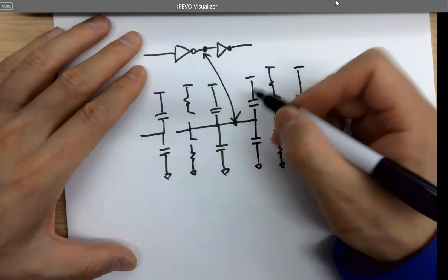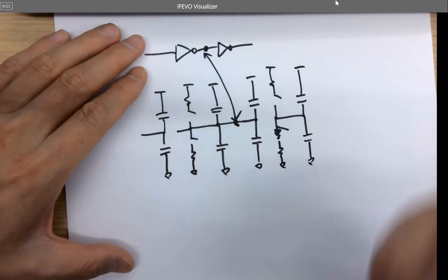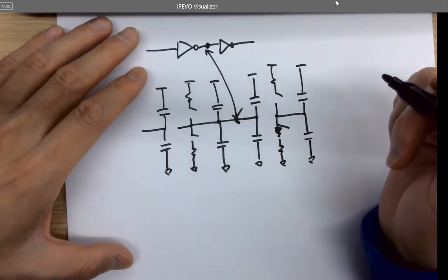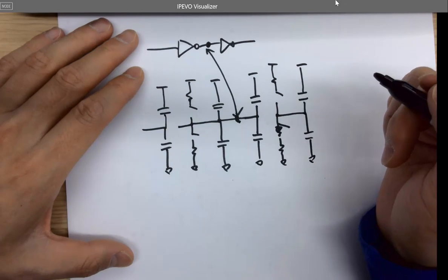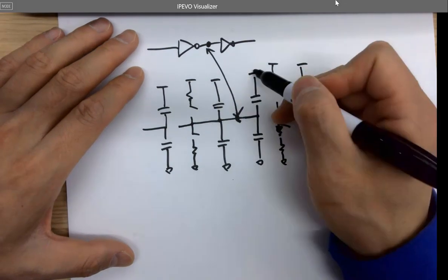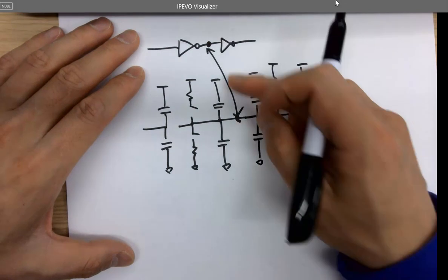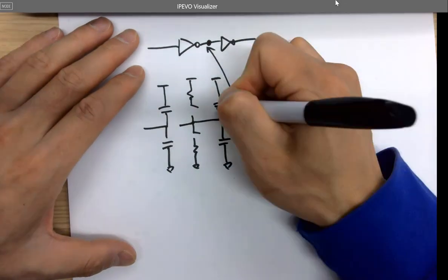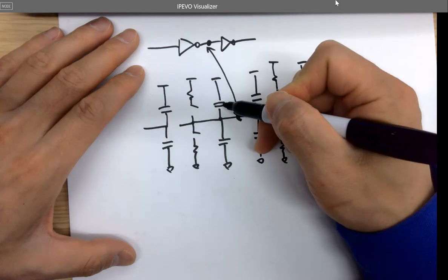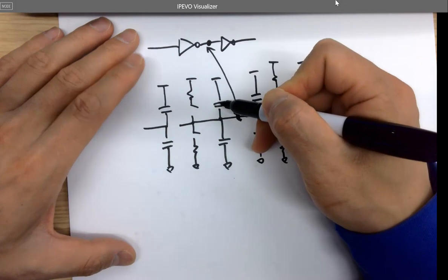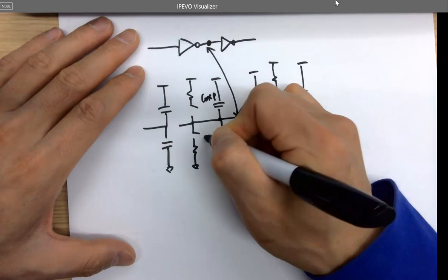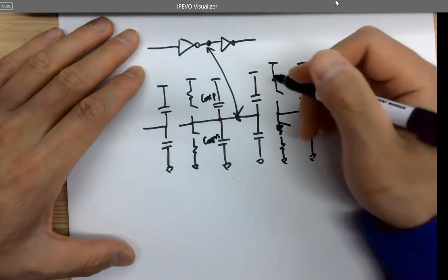So what is the capacitance at this point in the middle? The DC sources are AC grounds, so you rotate them and short them to ground. So we got 4 capacitors in parallel. And these are the output capacitors, which engage in the Miller effect, right? So this is COXP, COXN. What is this?